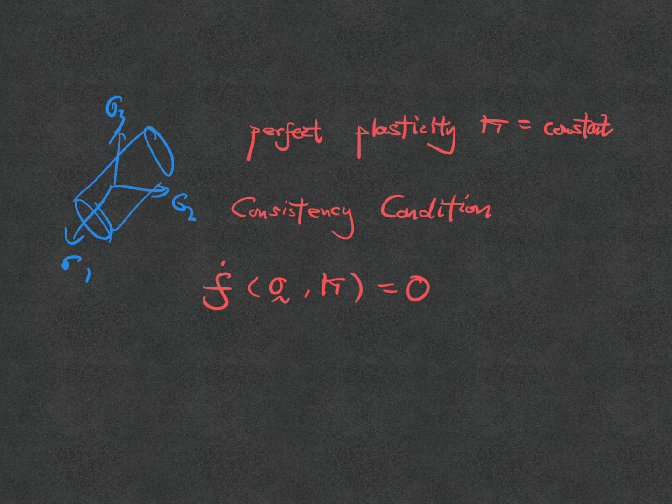In general f can change, but on the yielding point, f itself can evolve, but when the material is yielding, f is equal to 0. Okay, so if I write an elastoplastic stress-strain curve even in 1D, that would be sufficient. So this part is elastic.